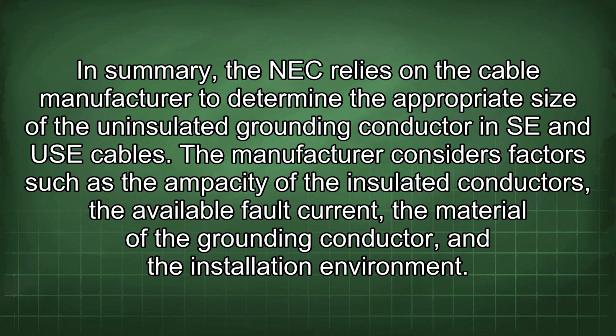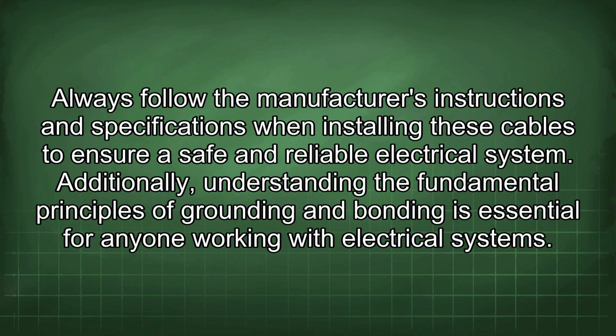The manufacturer considers factors such as the ampacity of the insulated conductors, the available fault current, the material of the grounding conductor, and the installation environment. Always follow the manufacturer's instructions and specifications when installing these cables to ensure a safe and reliable electrical system.